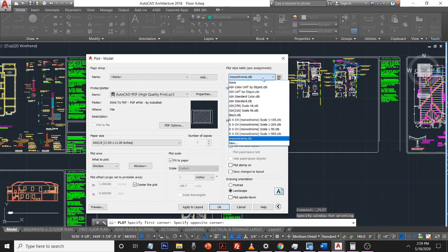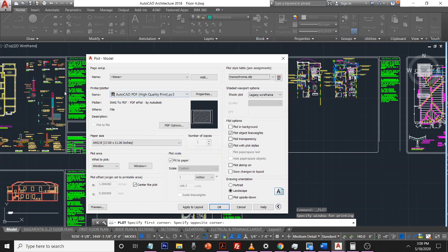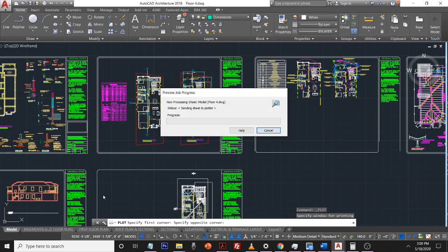The last option is to choose whether you want to print your drawing in color or a specific range of colors. For this case, and what you are also going to do is choose monochrome. And what monochrome does is turn all drawing layers to black and the black background to white. So if you notice, my drawing here has a black background and colored lines. By choosing monochrome, I can go to the preview tab and show you what that looks like.